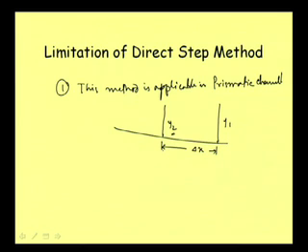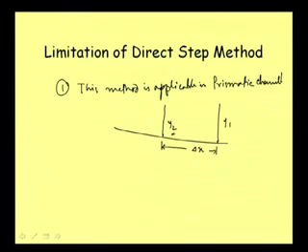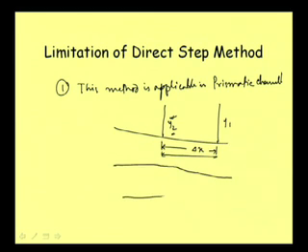And the equation we are using, the governing equation, there itself we made one assumption that the channel is prismatic. Okay. Now, when we are applying that equation and solving for delta x, we do not know beforehand what the length of this delta x is. After taking this y2, we are calculating this delta x. Now, it may happen that the plan view of the channel is like this.